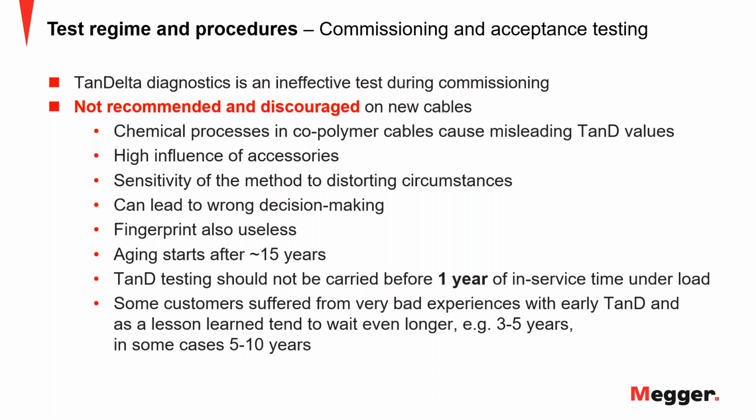No, modern copolymer cable shows a complicated aging behavior, and if you really want to do a tan delta test, if you really insist, I want to do this, even though it's useless, it's ineffective, you should wait until 1 year. Okay, so the cable should be in service under load, not just sitting there for a year. It should be in service under load for at least a year to prevent